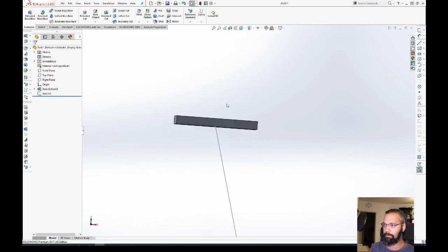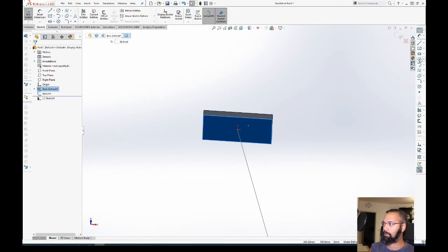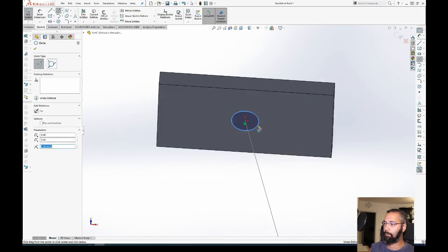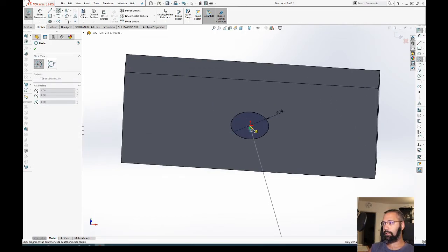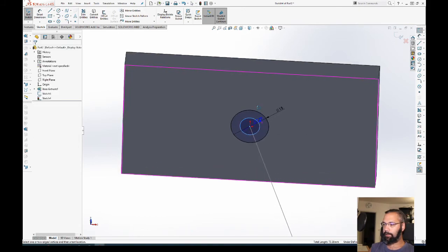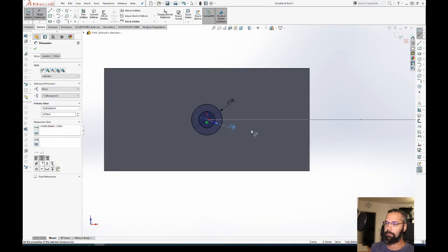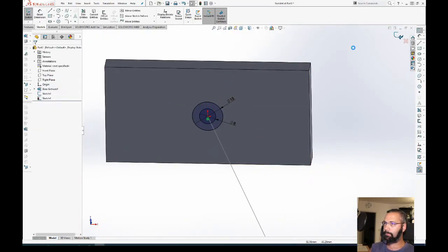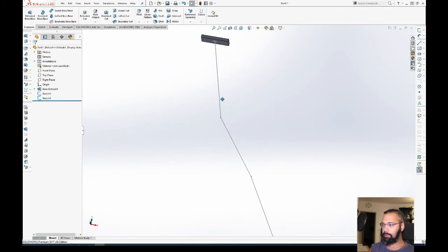You keep that sketch over there and you start another sketch over here. Let's say we want a circular profile, and that our profile, made of stainless steel, whatever, is 15 millimeters outer diameter, and in the middle you have another circle that's 8. Sounds good. All right, you save this sketch, and now let's see how this looks.